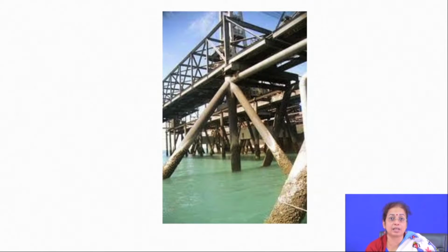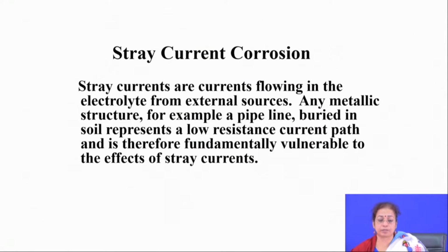So, what you have to do is that at regular intervals you have to inspect the corrosion rate of the corroded species, corroded magnesium, so that you can say whether your steel can be protected further. Otherwise, you can also estimate the amount or volume of the magnesium required for protecting the component for several years, or accordingly you can also calculate the lifetime of the component. So, this particular means is very widely used for protecting large structures against the corrosion process.